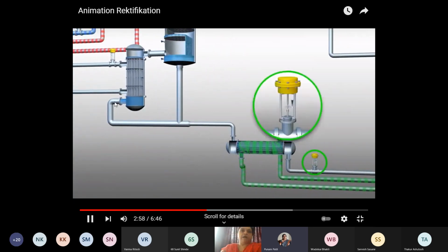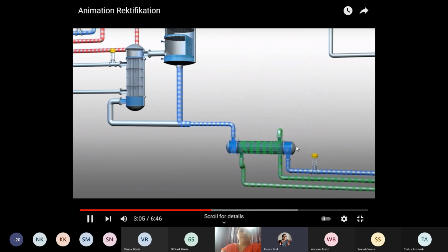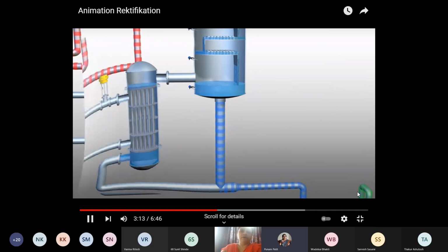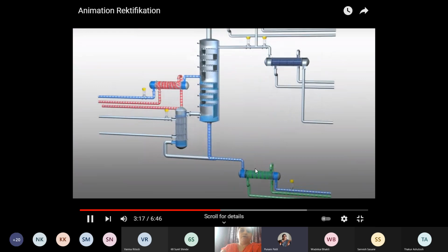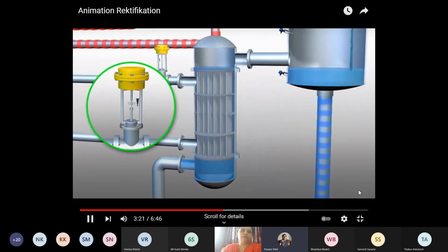That liquid is added to the reboiler where heat is provided, as well as that liquid is collected in this receiver. ये bottom product का receiver है. Okay, so that bottom product is taken away through this receiver. Maybe you require to reduce the heat of the bottom product. That's why cooling action is shown over there.